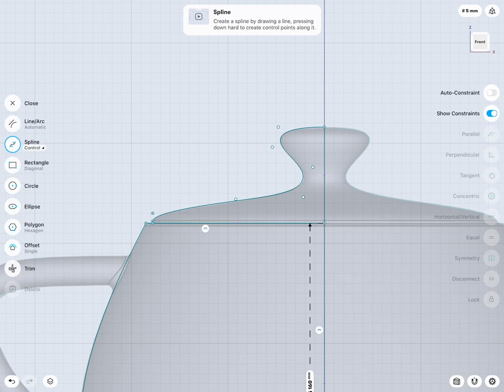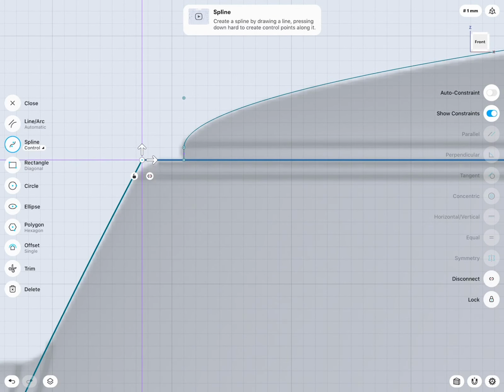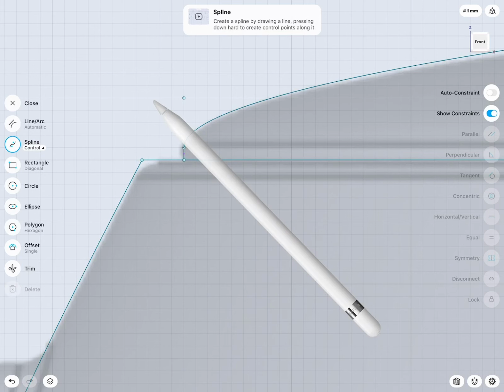The lid also has to sit on something, so it needs to be some sort of an interlocking mechanism. So let's see, what is this distance here first? This is 3.5. Okay, good. We can keep this 3.5. The material thickness of the main body will be 3, so we have a millimeter of clearance.